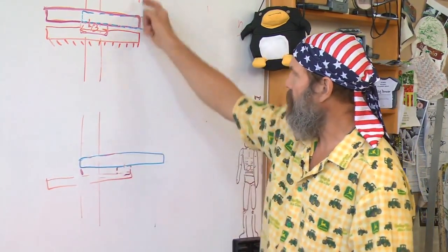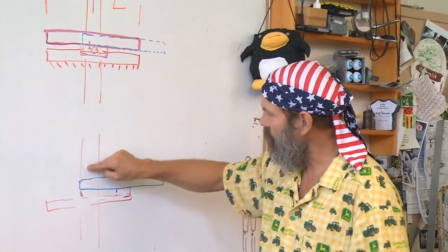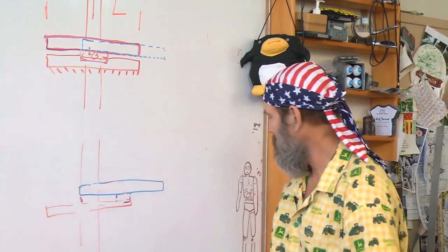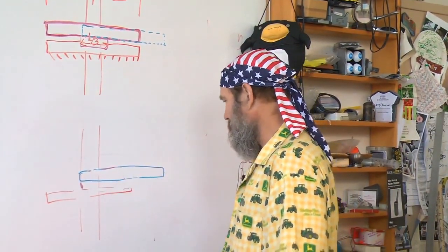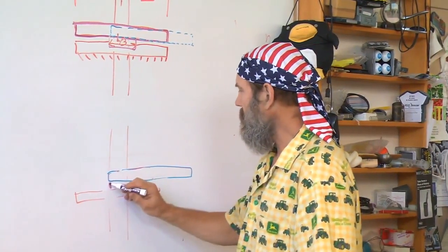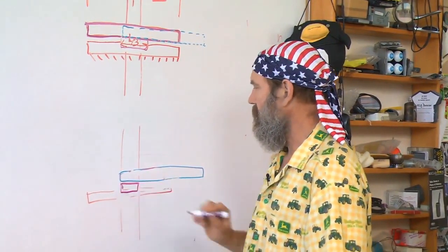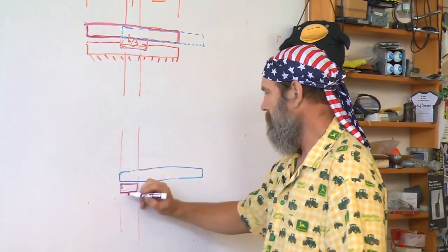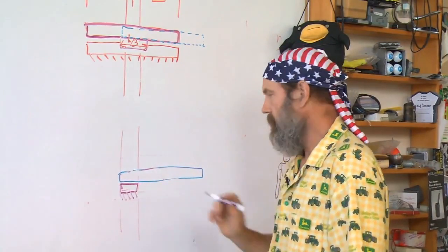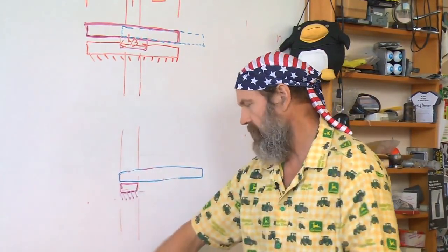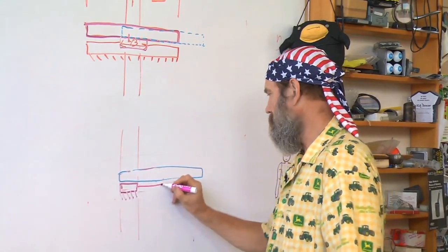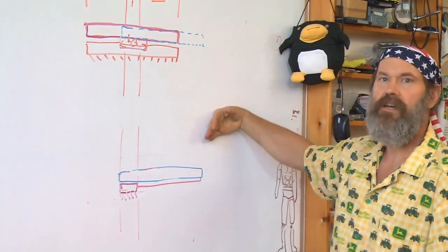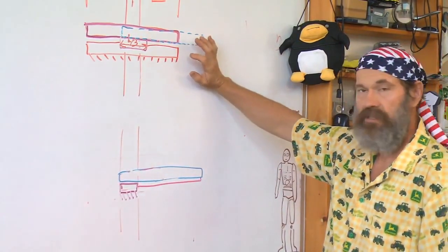The bearing block, the flow of forces, we want to always go from the tool into the part right back into the structure. Tight structural loop as opposed to this. So that tells me topologically in my brain, because I'm feeling the forces, that I'm going to keep the bearing block here, which means that a better design is to fix my bearing block and then have the rail for the bearing block on the table. See, this is the opposite of that, the reciprocal design. There are cases where this is better.